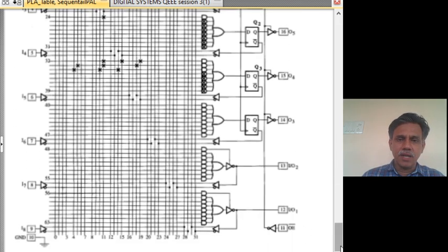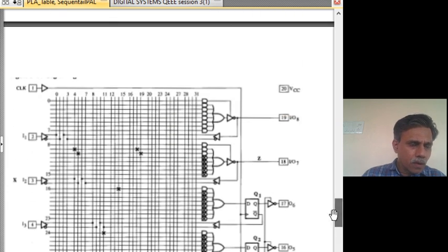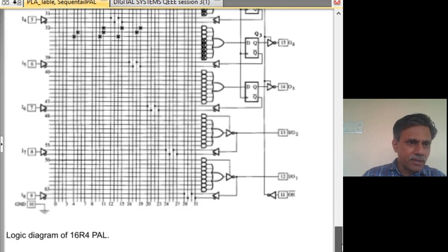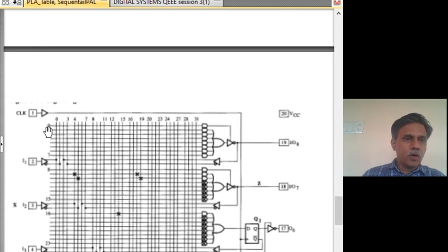It starts from, I believe, I0, I1 only, okay. I1, I2, I3, I4, I5, I6, I7, and of course, there is an I8 also. All 8 inputs are there. For each one of these inputs, you have two vertical lines going, one for the normal and one for the complement. For example, this would be the normal one. After buffering, the bubble is there. This would be an inverted one. This would be a normal one. These two lines, 0 and 1 line, stand for I1 and I1 bar.